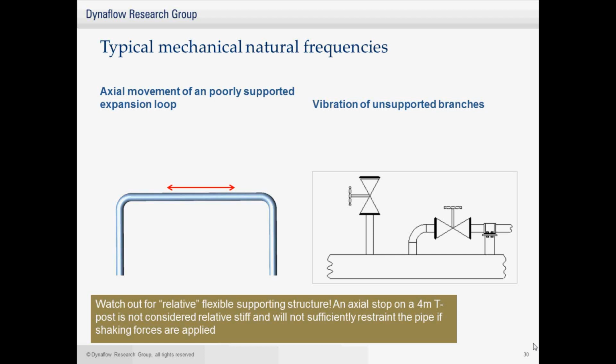That's typically a natural frequency. In that case, you should place an actual stop or something inside this expansion loop to prevent that natural frequency from occurring.